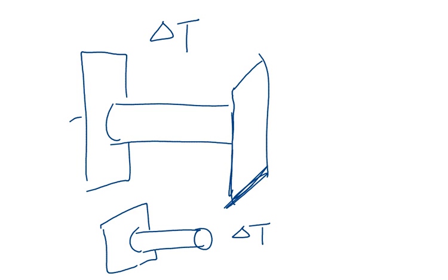How about in that top case? In the top case, there's no strain because this rod cannot elongate, right? It's being held in place. But you end up with a stress. So now you have a stress with no strain, right? And in the bottom, you have a strain with no stress. This would not happen with forces, right? With the forces, in order to get a strain, you must apply a stress. If you apply a stress, you must get a strain, right?